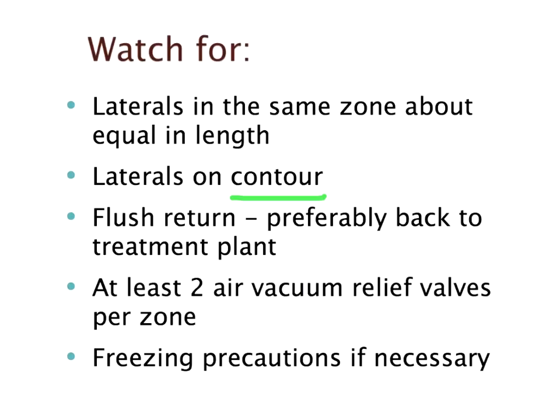Okay, flush return. Preferably back to the treatment plant, as I discussed before. You don't want to disturb the pump tank with the effluent going back to the pump tank. And again, if you're not doing it to save money, but just because it's not practical to go back to the treatment plant, which sometimes does happen. Sometimes the treatment plant could be a mile away from the drain field. In that case, I would suggest putting in a settling tank ahead of the pump tank, so that you flush to a settling tank, and then the overflow from the settling tank goes into the pump tank, so that you don't disturb the pump tank.